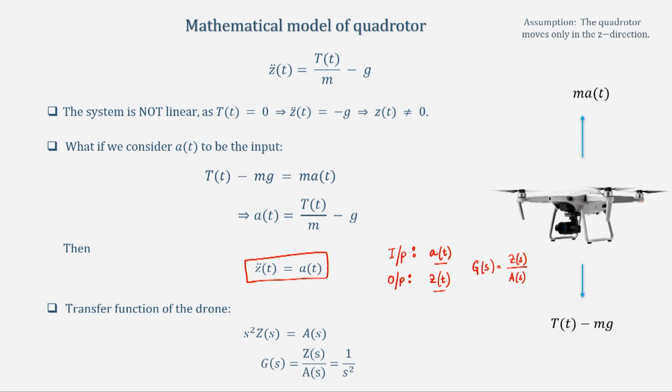Now, notice one thing, when the quadrotor moves, what is it that is making it move? The propellers, right? The propellers are rotating, as a result of that you are getting the thrust, you convert it to acceleration and then you know where to go, because you have the transfer function, you know how the system will behave. But when the propeller is rotating, it is basically a motor, right?